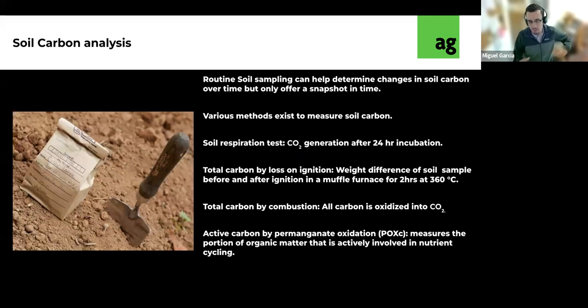And ideally, the entire field should have the same soil texture, same slope, all of that. But if it doesn't, then those become different subsections that you need to sample. If there are significant differences in the soil type, you need to make sure that you sample those separately to make sure that you get good representation. And then make sure that the same person is doing the sampling, or that everybody in your team knows the protocol and that everybody's following it properly.